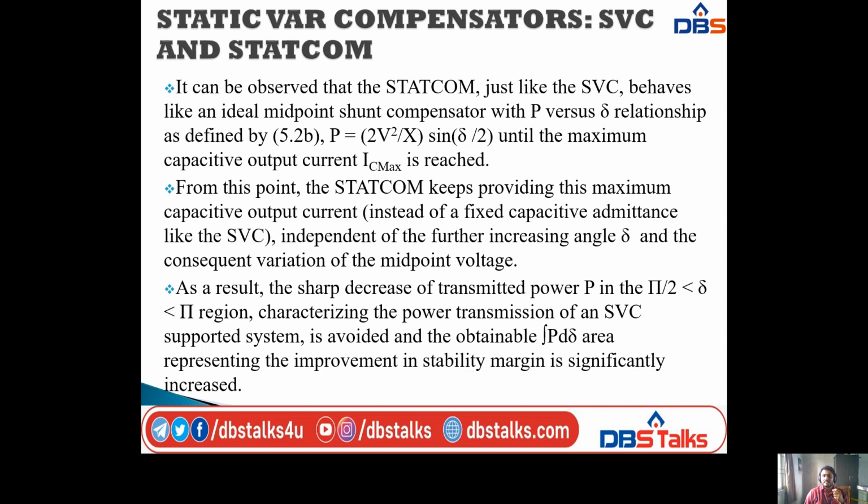So from this point the STATCOM keeps providing this maximum capacitor output current that is independent of further increasing the angle delta and the consequent variation of midpoint voltage. Why are we using this midpoint voltage? In this configuration I am using the midpoint connection only, that's why I am taking the midpoint voltage.